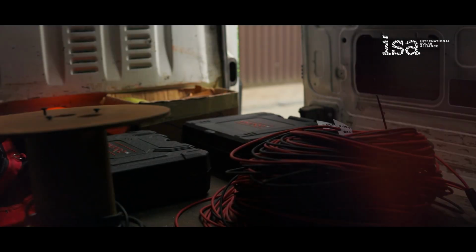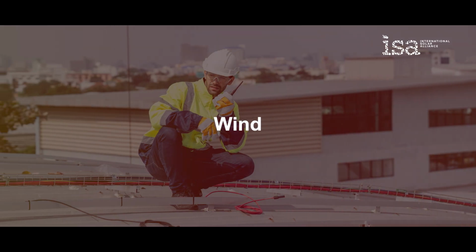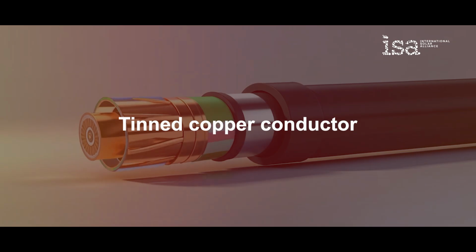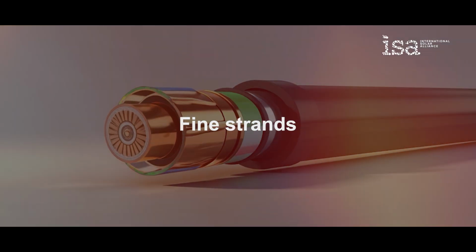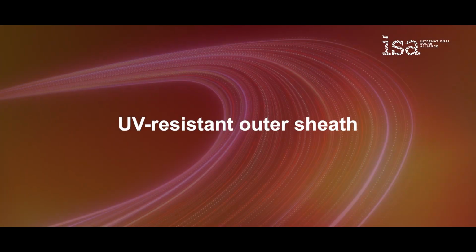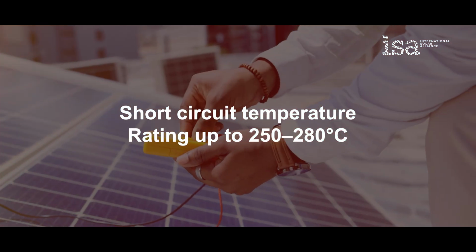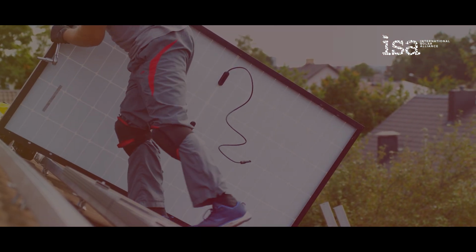DC cables carry direct current from the solar modules to the inverter. They are exposed to harsh sunlight, moisture, wind, and temperature variations. Key characteristics include tinned copper conductor for better corrosion resistance, fine strands for flexibility, XLPE or XLPO insulation for high temperature resistance, UV-resistant outer sheath, short circuit temperature rating up to 250 to 280 degrees Celsius, service life of 25 plus years.